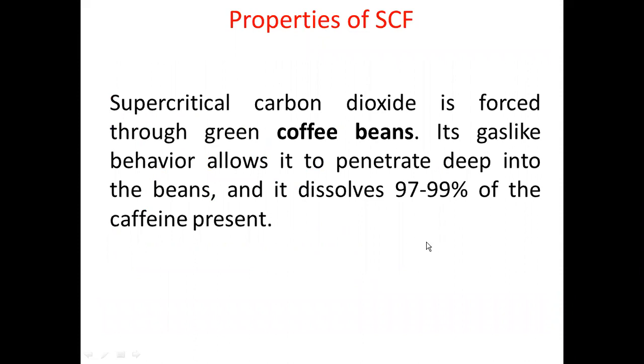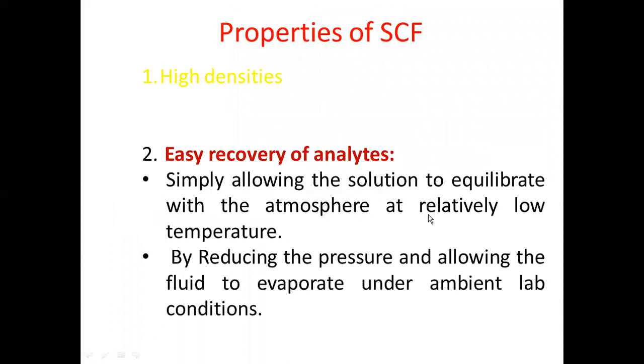So as an important application, you can remember the percentage of decaffeination. 97 to 99% of the caffeine can be extracted by this technique. Let us see that later. And as I told you, easy recovery of the analyte is always possible in supercritical fluid extraction, because we can allow the system to come to the equilibrium state by simply releasing the pressure, as well as the temperature.